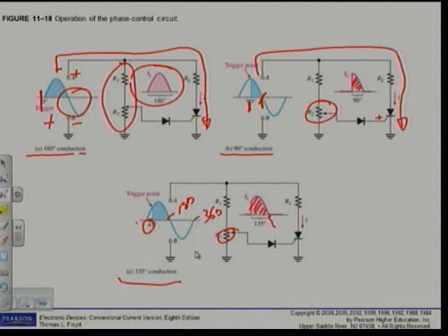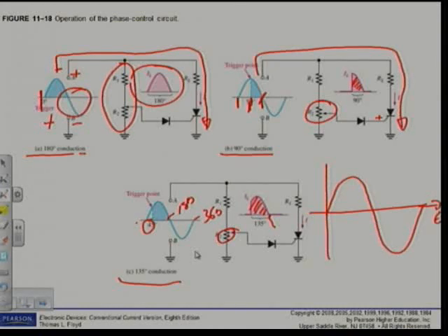All right. That is basically what we talk about as phase control. That means I can control the amount of power to my load. One important thing here, with a circuit like this, we can only control basically from 0 to 90. That means the control can only take place from there to there. All right, let me make another drawing. We look at this, we can only control from 0 degrees to 90 degrees. Why? I will show you why.